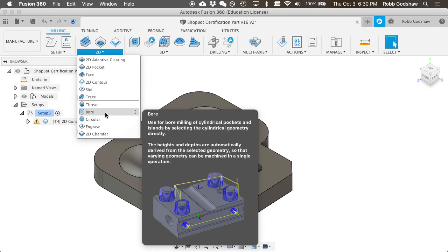Do you draw the dog bones in the interior corners by the eyes or the cheeks of the monkey face? Yes, you would if you cared about those corners. You don't need a dog bone in every interior corner. You only need to dog bone interior corners that are going to be interfacing with something that's square. Does that make sense? If you had an aesthetic reason that you wanted those corners to be sharp, your best bet would be to go in with a file after it's cut and just go until it's sharp. But yeah, that's a great eye.